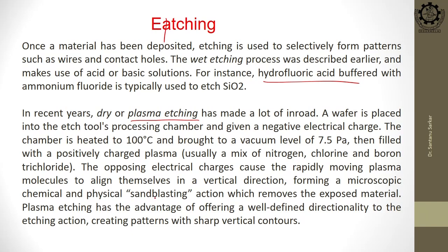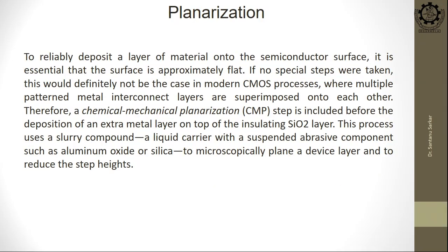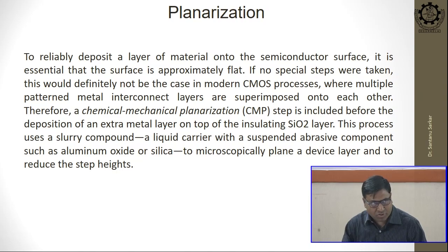Okay. So, sometimes in the case of ionic bombardment, a sandblasting kind of technique is also used, where rapidly moving plasma of opposite electric charge can go and collide and remove the material. So, this can also be used for etching. Okay. So, acid etching and dry etching, remember these two terms and concepts, that is okay. Planarization, that is mechanical or chemical planarization, any rough surface that is there, you can remove.